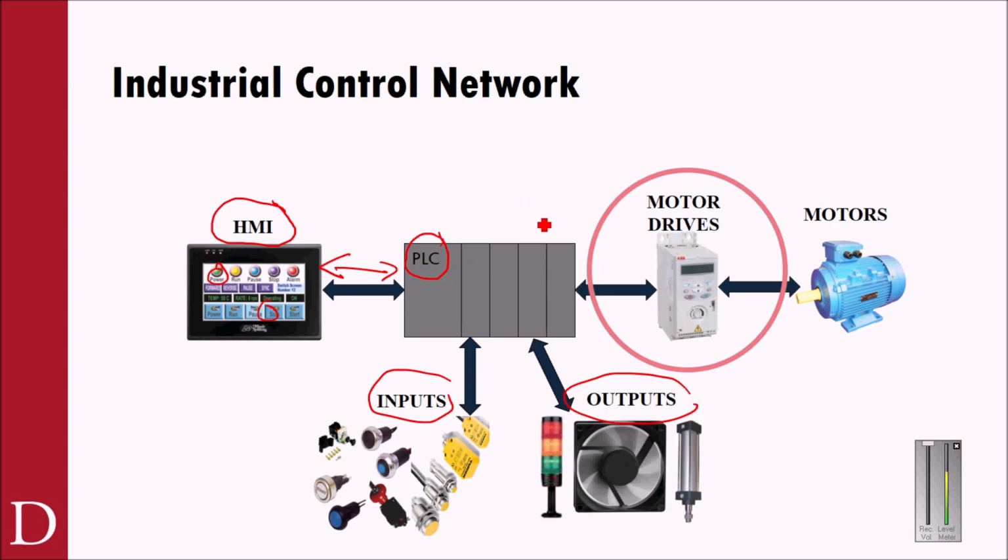But in a lot of cases, we need to run motors. And unless we're just turning a motor on or off, or in the case of a DC motor, we're using a DC drive, it's very common for us to be using what are called AC drives, or VFDs. That's this guy right here. And the beauty of the VFD is that it allows us to control AC induction motors, like this guy right here, very, very precisely. So it's not like a servo where we're concerned about shaft position, but it is about wanting to control speed, let's say.